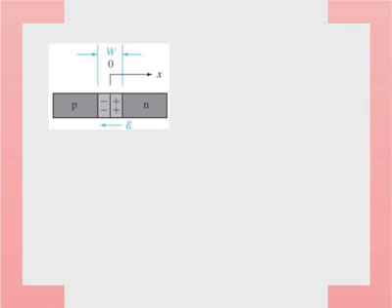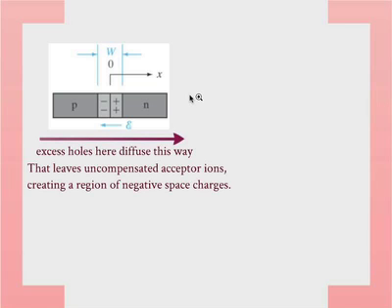Of course, outside this region is neutral. But within this boundary, you generate charges in this way. Of course, with this positive charge, negative charge, the electric field is this way, right? Which is what we just drew. Everything is consistent. That's the picture we drew here. So you have a distance W, which we can refer to as a transition region between the p-type and the n-type, where the charges exist. And the electric field is pointing that way. Outside, there are no charges. That's a neutral region.